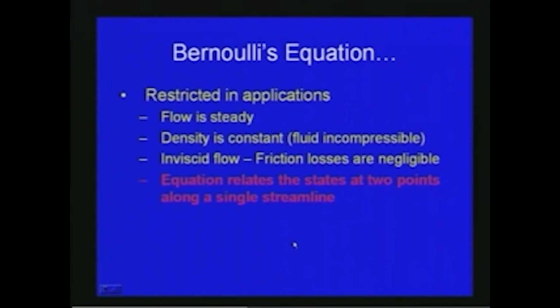As far as Bernoulli's equation is concerned, it has some restrictions. It is derived based upon the assumption that the flow is in steady state, so the time component is not there, and density is constant, so that the fluid can be considered incompressible. And then of course we also assume that the fluid is inviscid, so that friction losses are negligible. Many practical problems make these assumptions difficult to apply, but in certain cases we can approximate the flow, even if the viscosity is to be considered. Whenever water is concerned, since its viscosity is small, or air flow, where viscosity is small, we can use this Bernoulli's equation. So the assumptions are: flow is steady, density is constant, and inviscid flow.